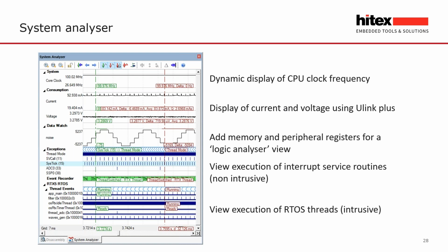We can take also information from the data watch trace, as well as putting that into a watch window. We can put it into the system analyzer so that we can gain a graphical view of exactly how the data in a variable is varying over time.